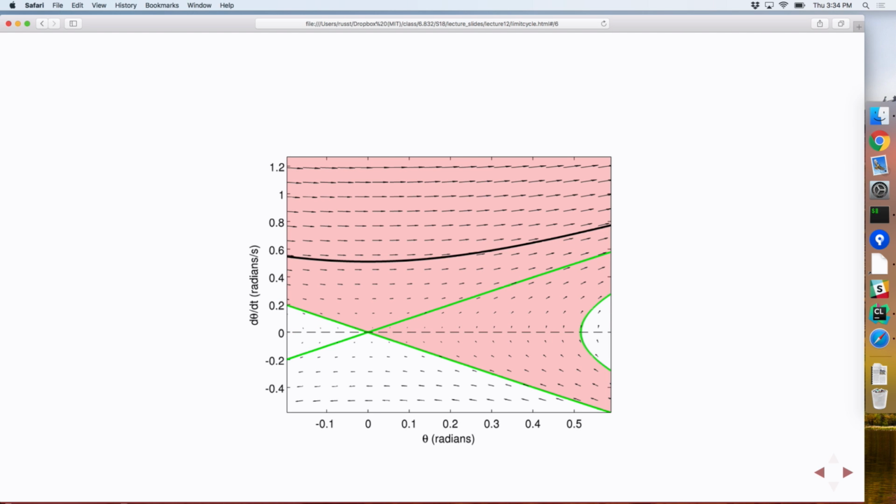So this is zoomed in to the crosshairs on the eyeball of the pendulum. The black line is my limit cycle, which goes back to there. The vector field is plotted for you, although the arrows don't show up at this pixel count. The pink area is the basin of attraction. Those are the states which were too slow, but they sped up, went around, and then started rolling forward. That was actually going uphill and then coming around and going forward.